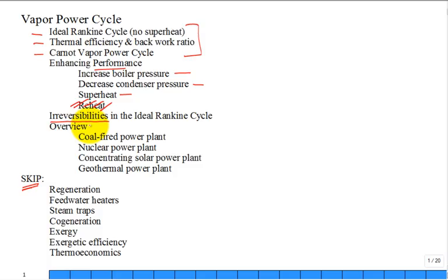And then we can add irreversibilities into certain locations, typically in the compressor. Not the compressor, I'm sorry. The pump and the turbine. We can add irreversibilities and redo the calculations. Irreversibilities in the turbine and irreversibilities in the pump will only degrade the performance of the system. It won't enhance it. But that's the reality of real friction in the system.